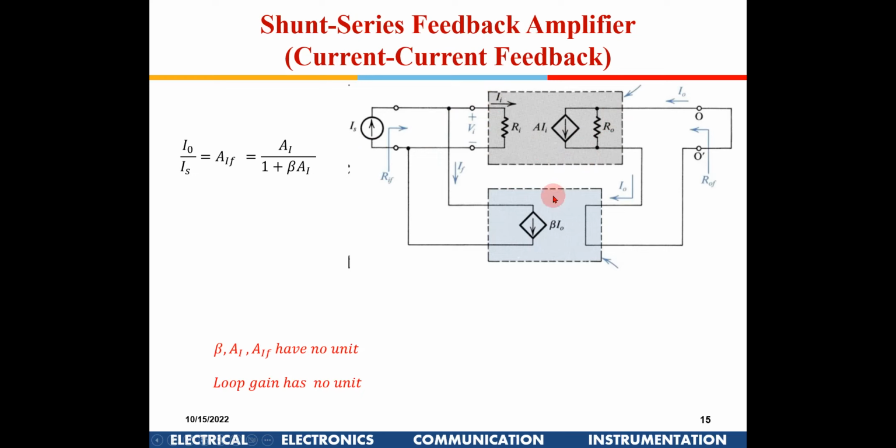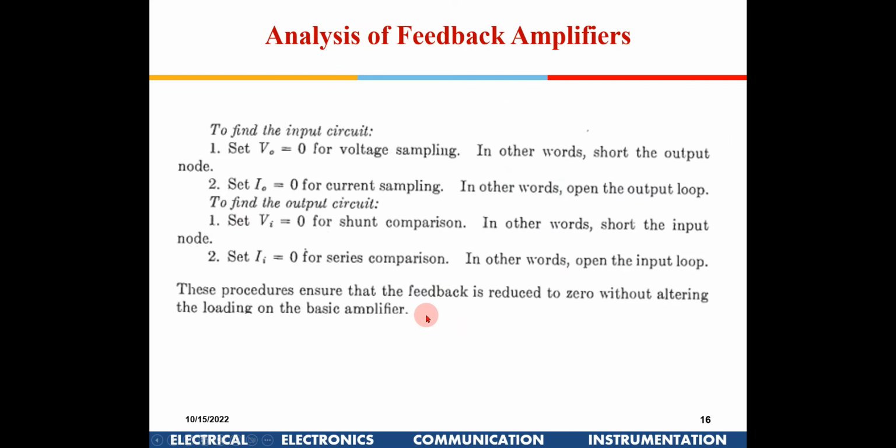In this case, can somebody tell what will happen to the output impedance? Increases. Output impedance increases. And input will be decreased. Input will be decreased, yes, because it is in parallel. Okay, input will decrease and output impedance will increase.